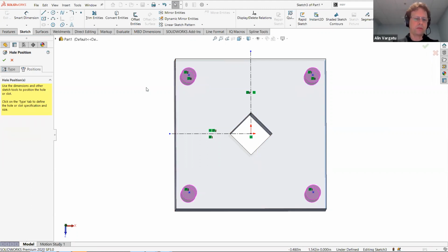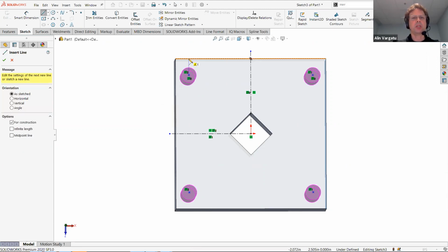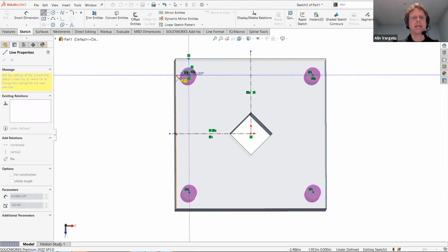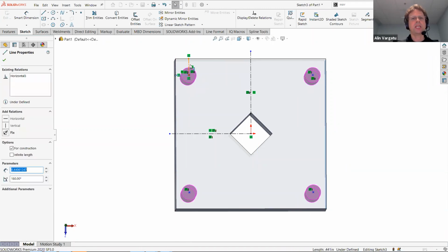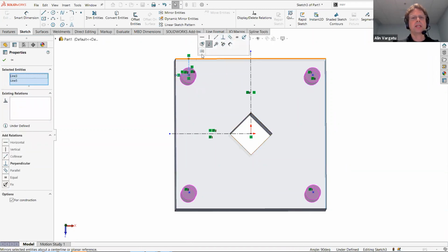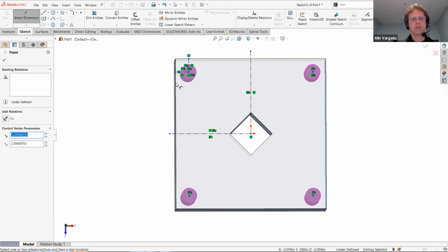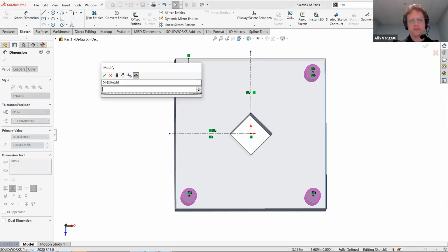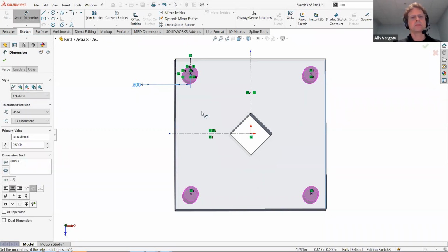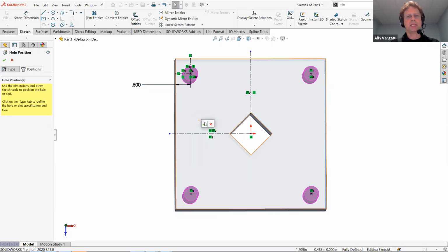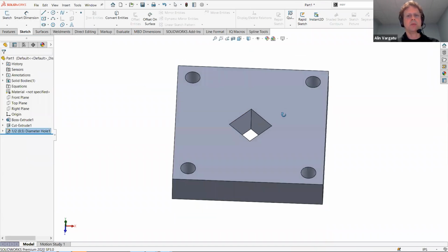And that is just a matter of finishing up with a dimension. I say one dimension because I tend to like to add construction geometry if I can, right? So like Jamie did in his demonstration, because in this case, I can use only one dimension to fully define my part. Let's press D and D again, and we are done.